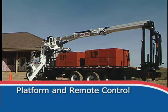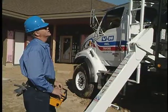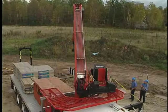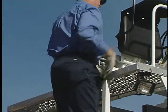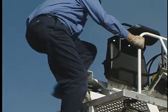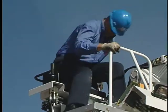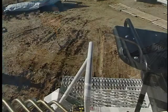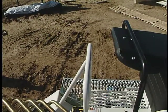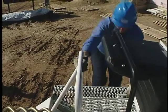Let's review the control systems. Cranes from V&H will offer you either top seat control, radio remote control, or both. As you saw in the pre-trip inspection, whenever you climb up to the platform control, always follow the 3-point rule. Make sure you're in firm contact and grip with hands and feet on at least 3 points of the ladder. Never carry items in your hand while climbing a ladder.